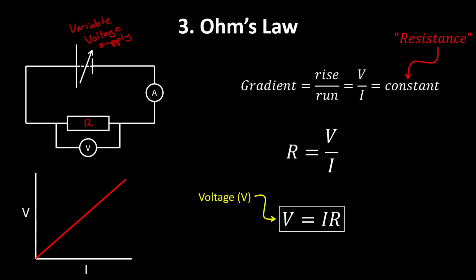So this is voltage, V equals current in amps multiplied by the resistance. Resistance is measured in a unit called ohms. It's actually, an ohm is a volt per amp if we just do our usual thing of smush it together and name it after a dead guy, okay? And it's got the symbol capital omega, okay? Sorry, the unit. Resistance is capital R, okay? So those are the three fundamental things. Kirchhoff's voltage rule, Kirchhoff's current rule, and Ohm's law. Those are the three things we're going to be using for solving these circuits.